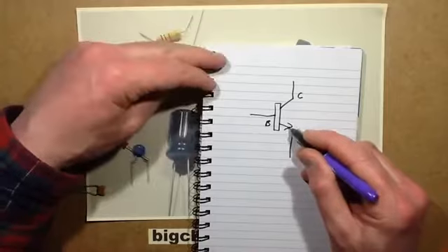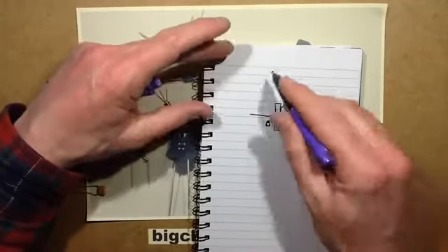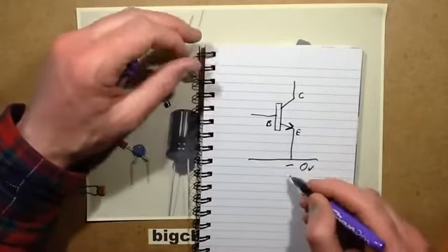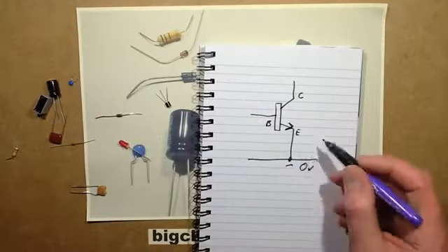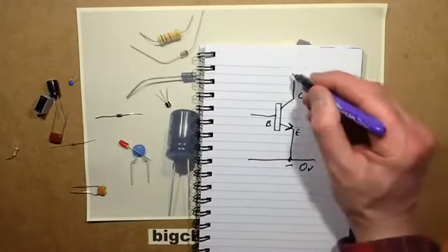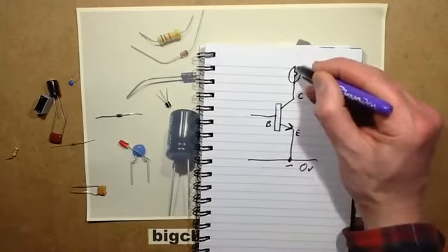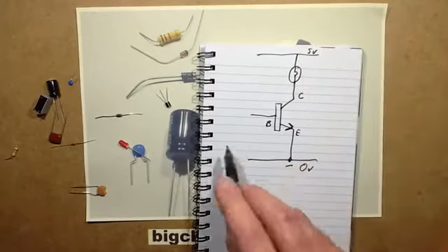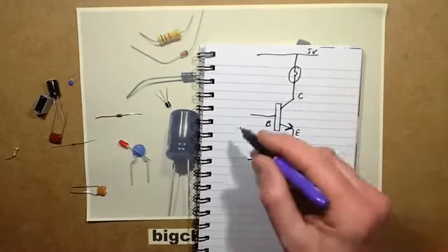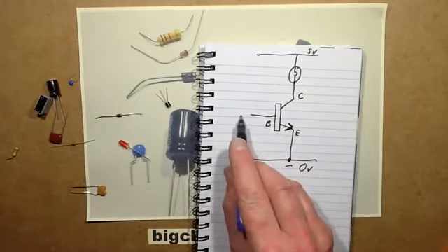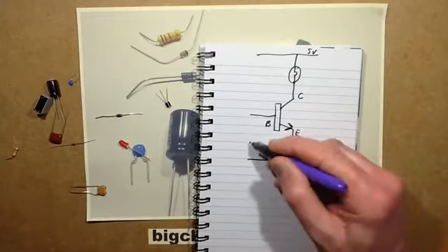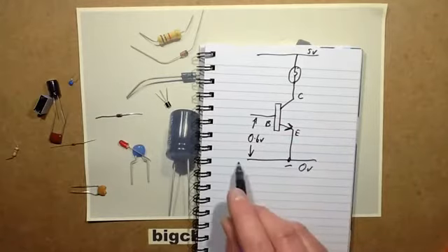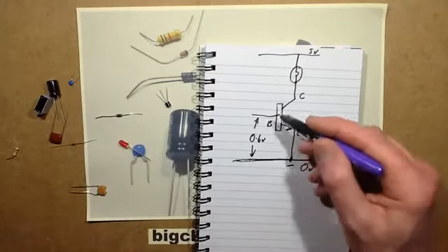In the case of an NPN transistor, it's usually switching something down to the ground rail, the negative rail, or the 0 volt rail. And it's used as an amplifier or switch. Supposing, for instance, you had a small tungsten lamp and you had a 5 volt supply. If you wanted to turn the lamp on and off, but you only had very limited current available, you can use a transistor, and as soon as you exceed about 0.6 volts, because it's silicon again, that's the standard silicon junction voltage, above the ground rail here, the 0 volts, and